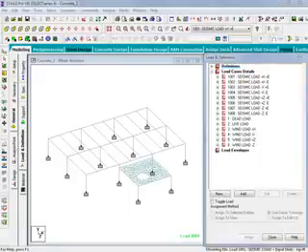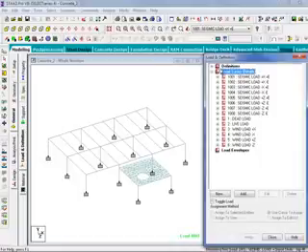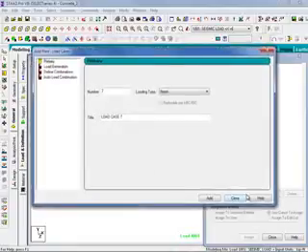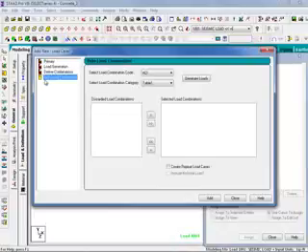When you are ready to generate your load combinations, you need to go to the Load and Definition dialog and highlight the Load Case Details option. We would then click on the Add button, which will automatically bring us to the Add New Load Cases dialog. From this dialog, we can define manual load combinations or use one of the load combination generators available in STAAD.Pro. For this training, we are going to use one of the auto load combination generators, so I'll select the auto load combination option.